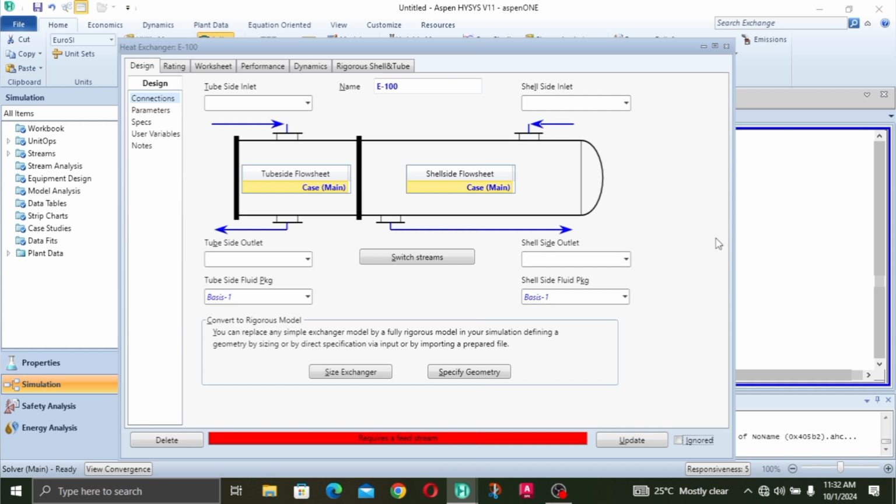And this is not desired when carrying out operations. So instead, you put the more hazardous fluid inside the tube, and you place the less hazardous one inside the shell. By this, when you have a leak from your shell, the non-hazardous fluid is the one that leaks out, which isn't much of a problem, and can easily be handled.